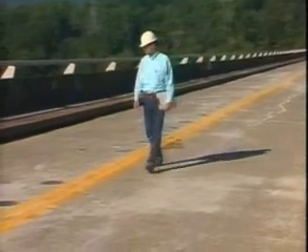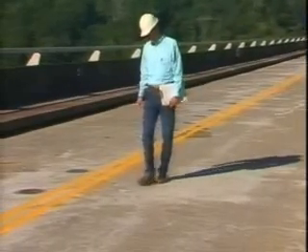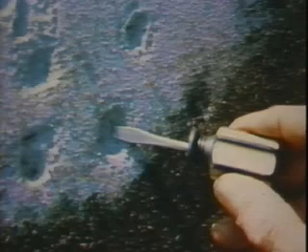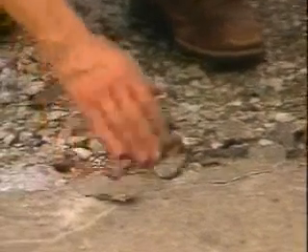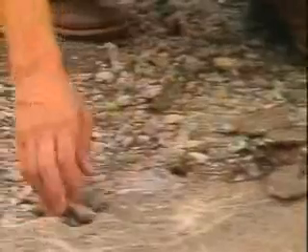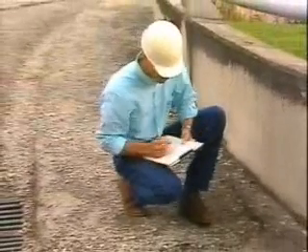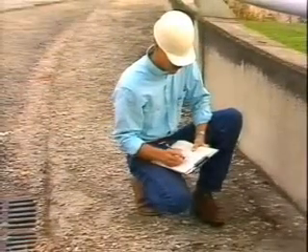Another problem you may encounter on the crest, as well as at other locations on the dam, is concrete deterioration. Types of deterioration include disintegration, spalling, pop-outs, pitting, and scaling. When reporting on concrete deterioration, be sure to include measurements, sketches, photographs, and an adequate description of the location.